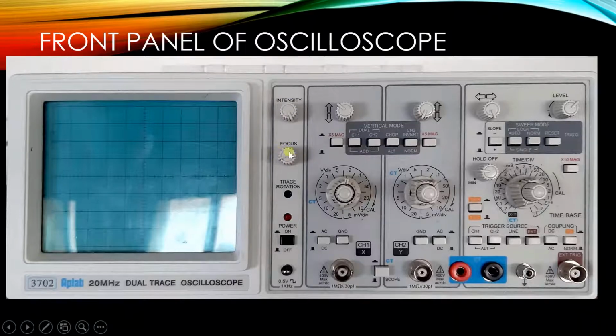This is the focus. Here we focus, meaning we make the waveform thicker or thinner, and this is our on off button and this is the on off LED. This button is the up down control of the waveform of channel 1. This is again the up down control of the waveform of channel 2, and this is the horizontal control of the waveform of the CRO.